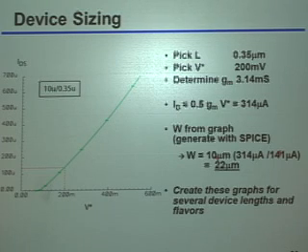By the way, just to make sure it's clear, people will sometimes refer to this kind of methodology as a so-called constant current density methodology. What they really mean by that is that, again, you choose a V star that sets the current density, and therefore all of the design simply involves scaling off of, or choosing an exact device width based off of, a known current density. Okay? So again, in order to actually do real designs, you're going to have to create these plots for lots of different types of devices, lots of different channel lengths, and so on and so forth. But I guess the good and the bad news is that's exactly why you had this as problem number 3 in your homework, so that you'll be able to use these moving forward when you do designs in this particular technology.